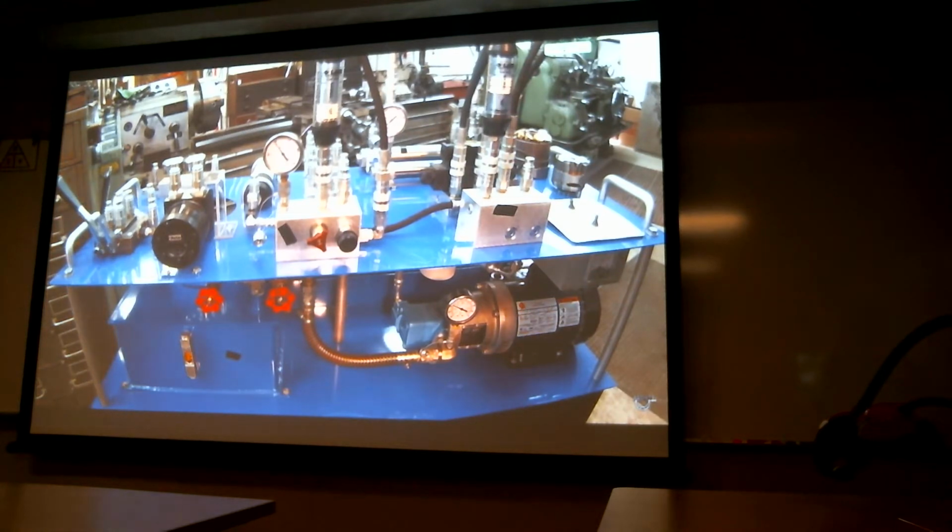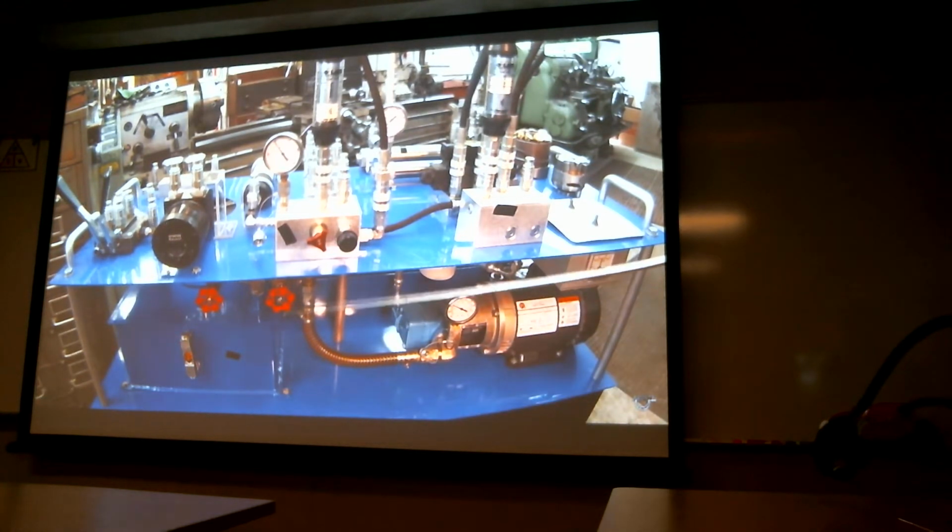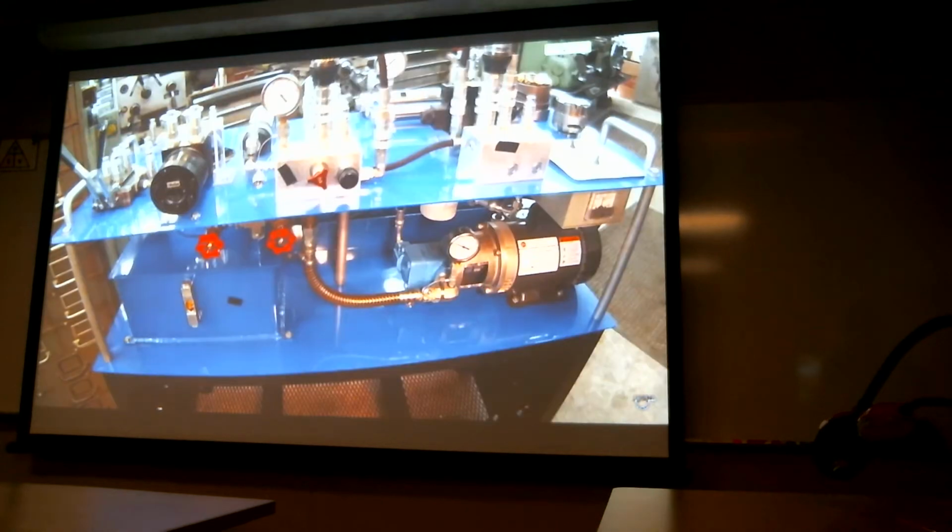What he's going to do first of all is start shutting this valve off a little at a time. And what you're going to see is little vapor cavities start forming in this hose right here. What I'm doing is starving the fluid into this pump, and the oil actually starts boiling. Those are the little vapor cavities you're going to see right here.